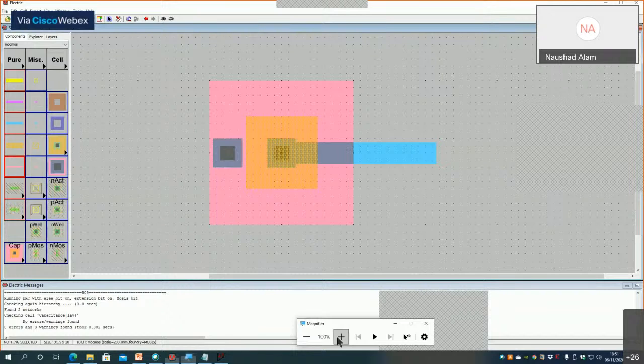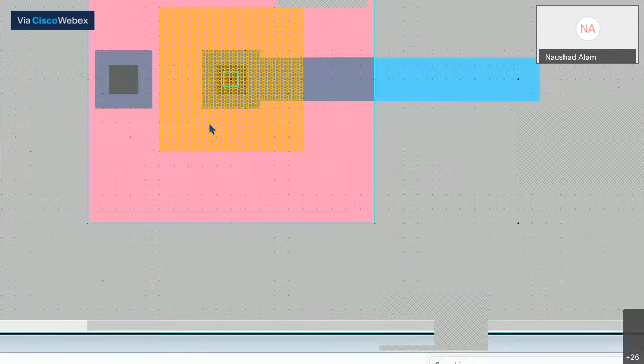So this way, now you can actually take a metal contact. I select here, and then I can bring the metal line out. So you can adjust it. Now you have got the two terminals. If this metal line is wide, I can select a pin here, and then I can connect a metal. So this way you can get a capacitor.